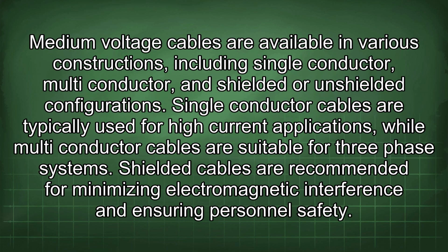Medium voltage cables are available in various constructions, including single conductor, multi-conductor, and shielded or unshielded configurations. Single conductor cables are typically used for high current applications, while multi-conductor cables are suitable for three-phase systems. Shielded cables are recommended for minimizing electromagnetic interference and ensuring personnel safety.